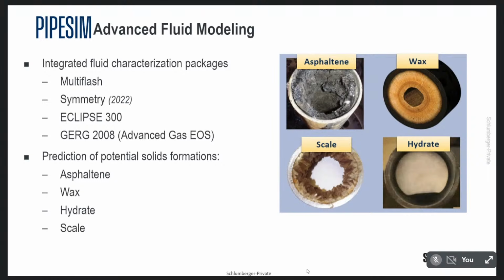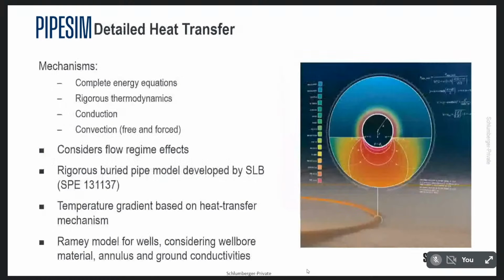For scale, Pipesim can model a scale concentration or predict solid or scale concentration by using a PVT file created from Scale Chem, which is software from OLI. For that, you will need to purchase your own license from OLI, create this PVT file, import it to Pipesim, and then Pipesim will be able to predict scale deposition for you.